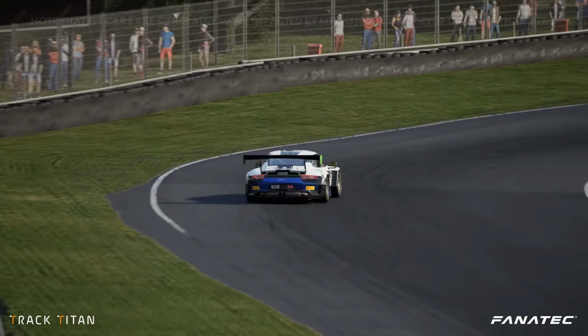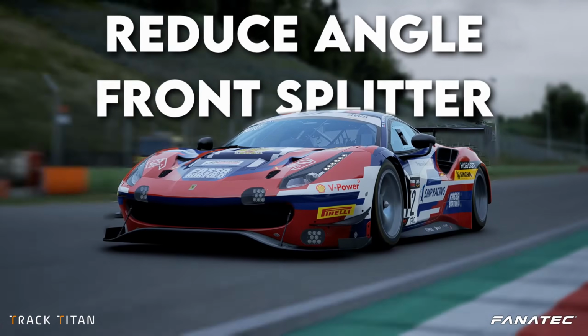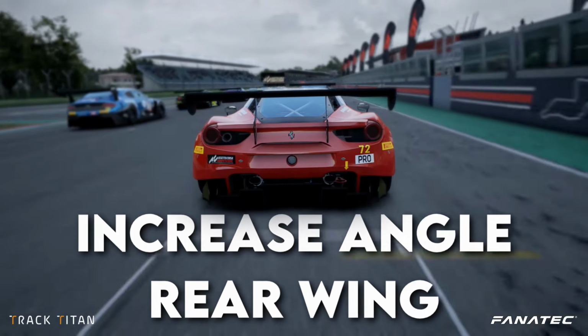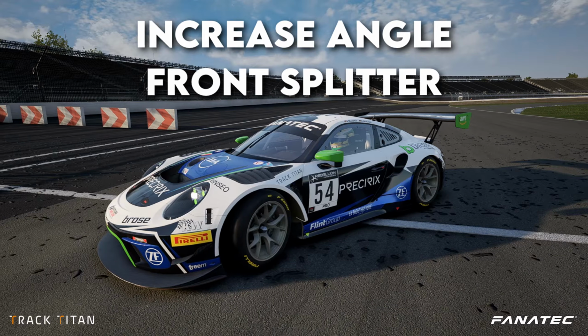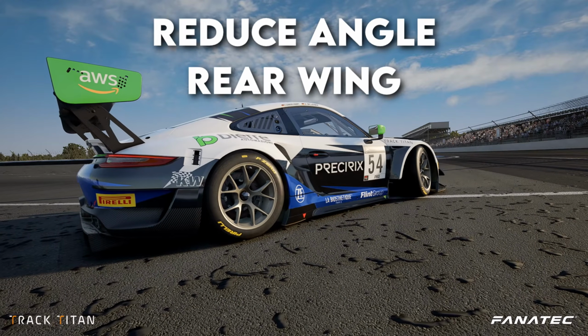Now, if the car feels oversteery during the fast corners, you might want to reduce the angle of the front splitter a little bit or increase the angle of the rear wing, whichever is possible. Now, if the car feels understeery in those faster corners, try the opposite. Maybe a higher angle on the front splitter or a lower angle on the rear wing.